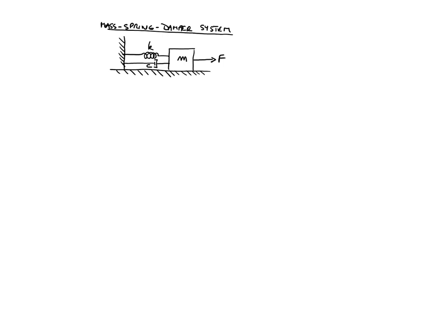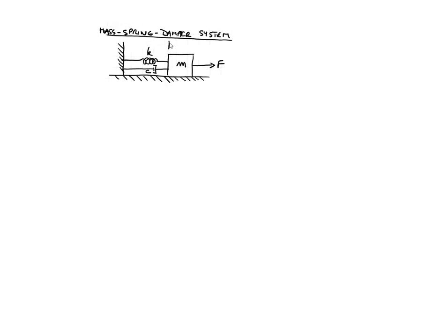We'll start with a very easy mass spring damper system that is shown on the screen, and we can write the equation of motion by simply writing, we assume here that x is this variable here, mass times acceleration, so mass times x double dot. There is the force of the spring, so minus kx, because it's acting in this direction here.